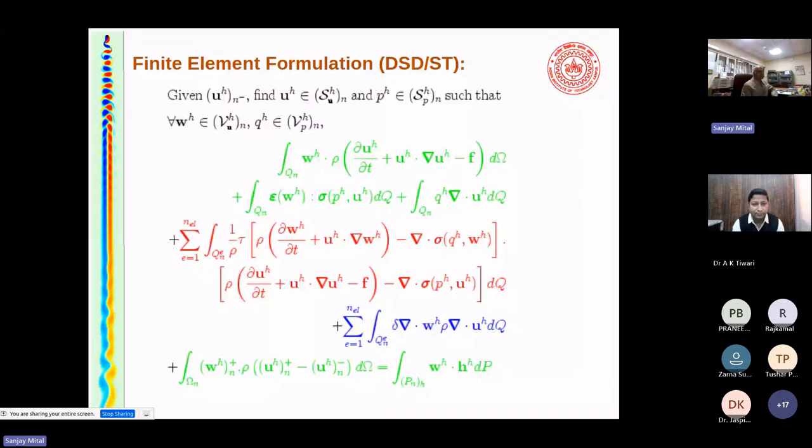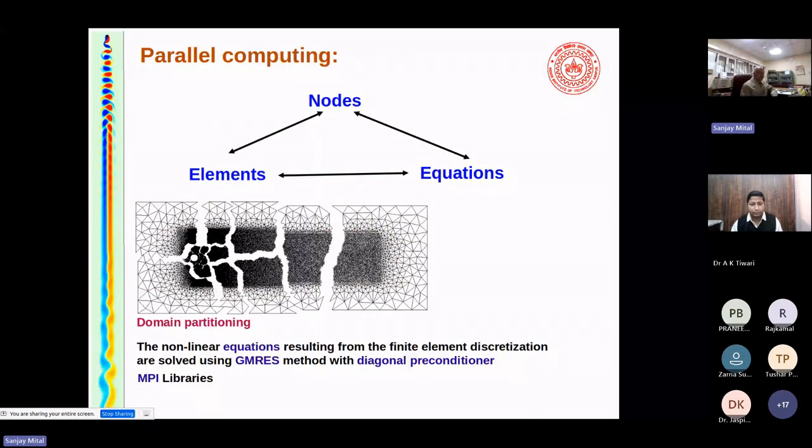The green terms are essentially the Galerkin terms, but one knows that Galerkin methods produce instabilities. So we usually stabilize them. And the red terms are essentially the least square terms on the momentum equation. And the blue term is the least square term on the stabilization term for the continuity equation. Then we can incorporate the boundary conditions, both Dirichlet and the Neumann type, but I'm not going to spend time on that.